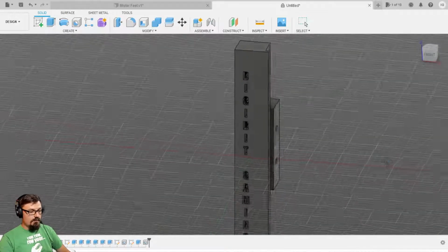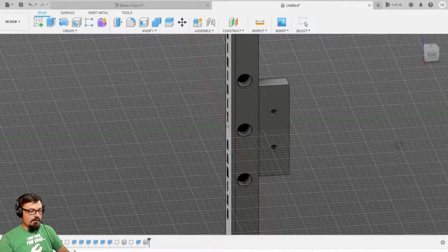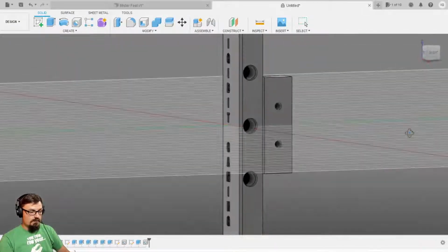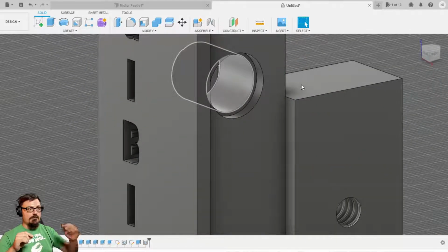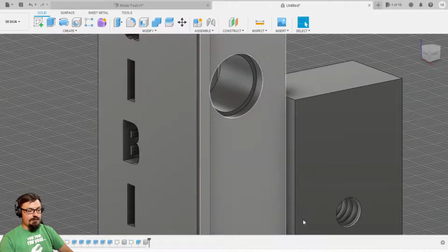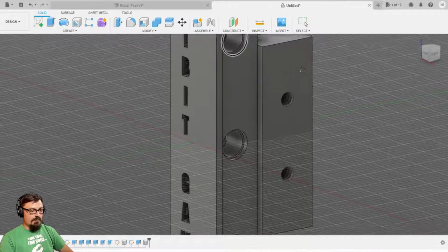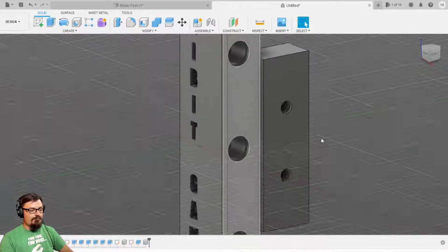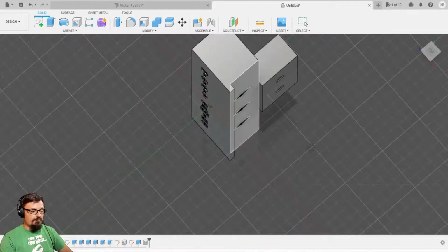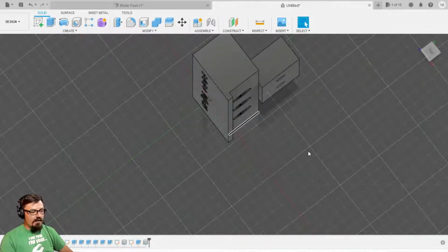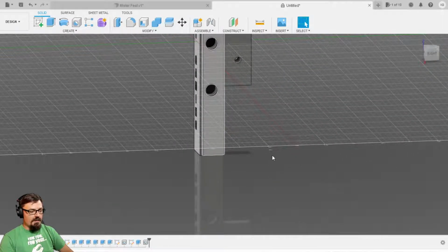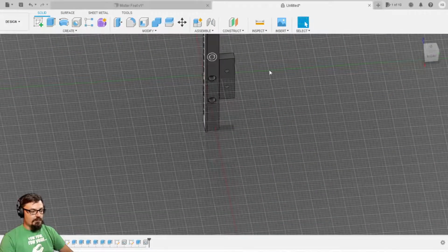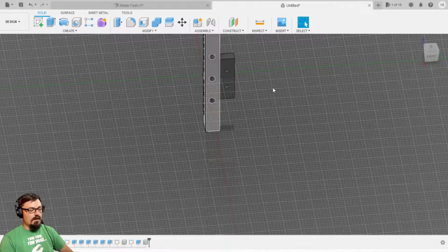And then we have our 3 LED holes, and this is spaced perfect, so the 5mm LED will just plug straight into these, and then you'll be able to wire it together. This channel should be fairly close enough to where I might make a little zip tie tab or something, but you should be able to run the LEDs down or up.